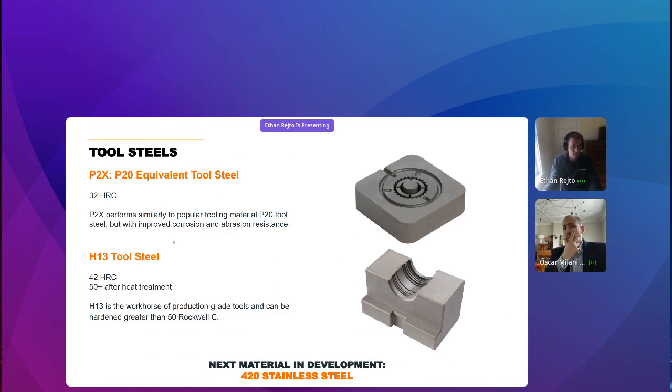Nice. And while we're on the topic, a quick question that's come to mind is what kind of sinter densities are we looking at with the Mantle parts? Yep. After all this, we achieve a 97% and above density, which we have proven to be fully adequate for molding applications. As I've shown you, we've molded millions of parts, abrasive resins, high temperature resins, fully adequate for that.